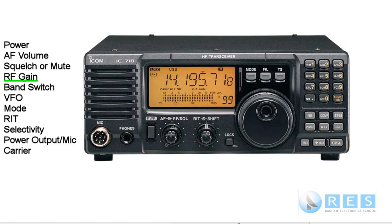And the RF gain is this control here on this radio. So you would rotate that RF gain in a clockwise direction to increase the receiver sensitivity. If your mute was open, if your squelch was open and you rotated your RF gain up, you would hear the noise increase.